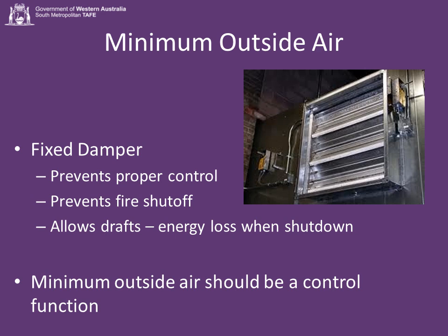One way that we used to do this is we used to just disconnect the last of the louvers off of the damper, jam it open, and then screw it in place so that it was always open. Now this is just shocking, if not vaguely illegal. It's a terrible thing to do. It doesn't give us any outside air control. It prevents proper control. You can't close the damper ever. It's like having a window propped open all the time to supply outside air.